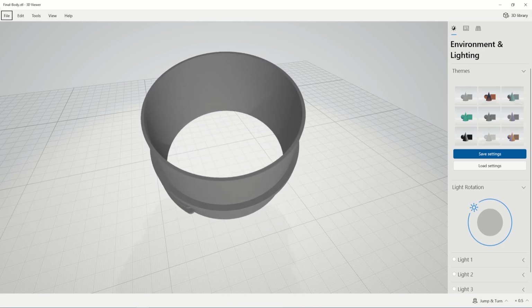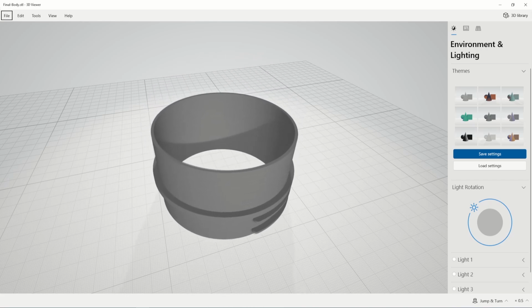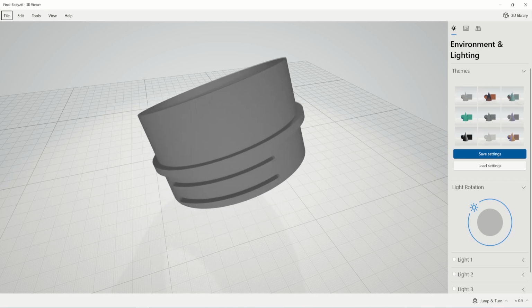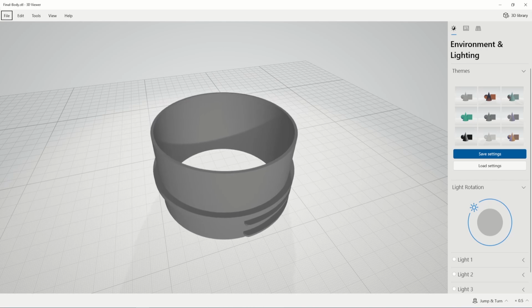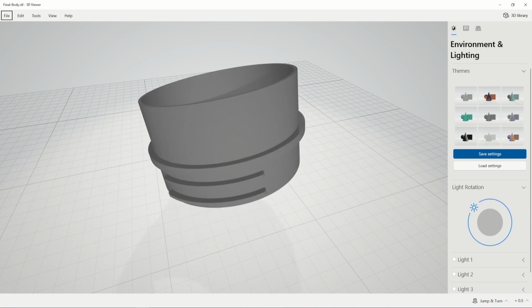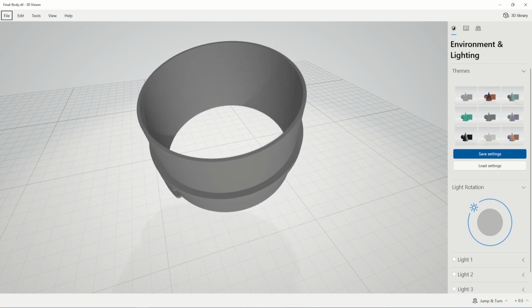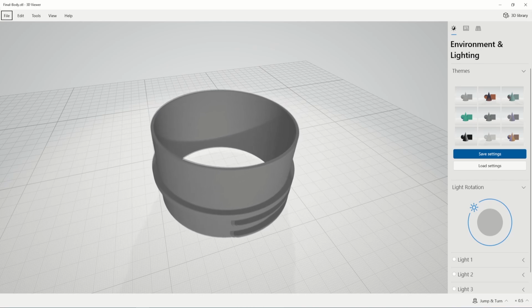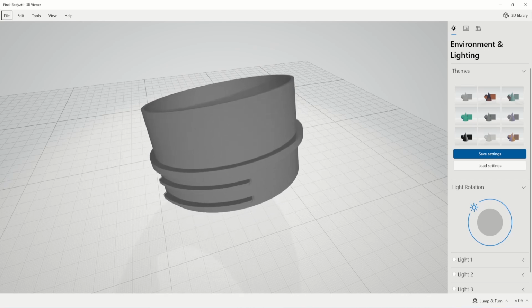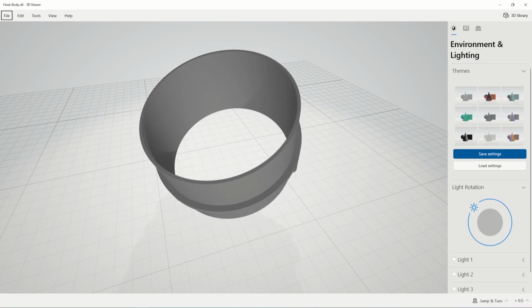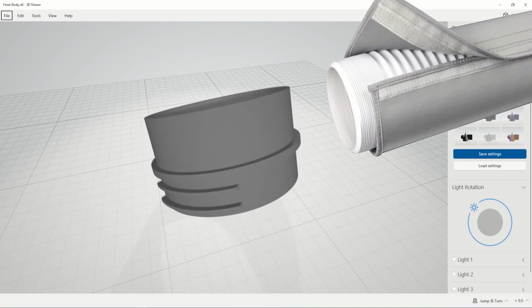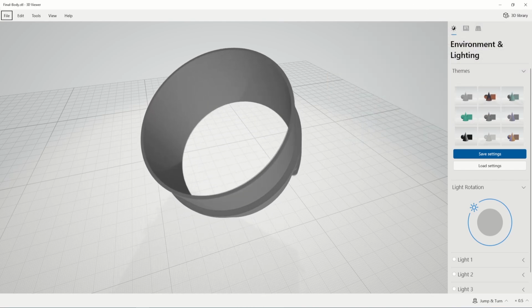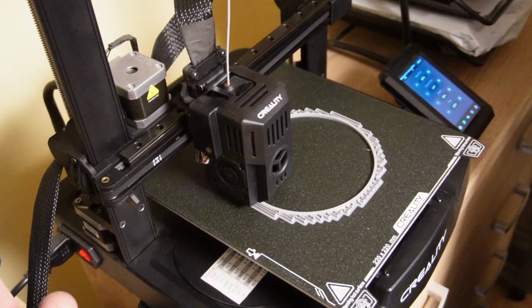Since the air from the air conditioner will be hot, I will use PETG filament to print the part. PETG can start to deform under load at temperatures around 80 to 85 degrees Celsius, so I hope it will be enough. Just a friendly reminder, if the hose of your portable air conditioner is too long, buy insulating sleeves. They are very effective in preventing the heat from the long hose from getting back into the room.